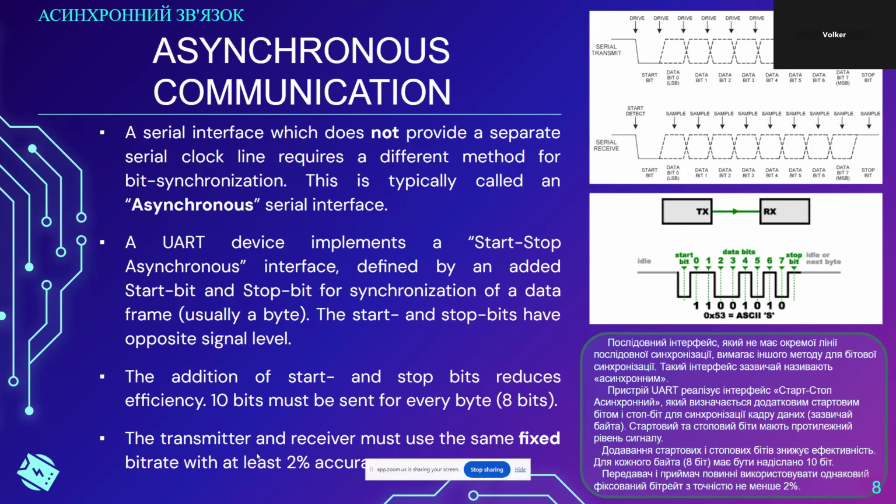Its own clock generator is also called a baud rate generator. It will start sampling the first bit after 1.5 bit times have passed. And from then on, it will start sampling the data line every bit time. That is demonstrated in the image in the upper right-hand corner, on the bottom, where it says serial receive.